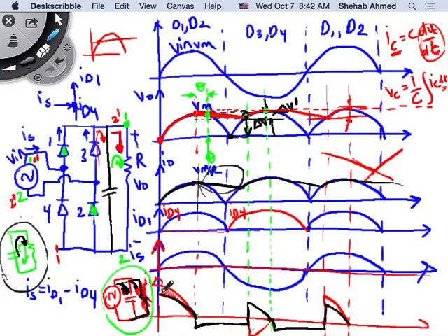So we reduced this a little bit, and then we drew some waveform here. And then we said that what's happening here, beyond this point, which I drew equal to pi over 2 just for simplicity, beyond this point, the capacitor is feeding the resistor. It's not the source, right? The capacitor is feeding the resistor in this case. And it's flipping its polarity.